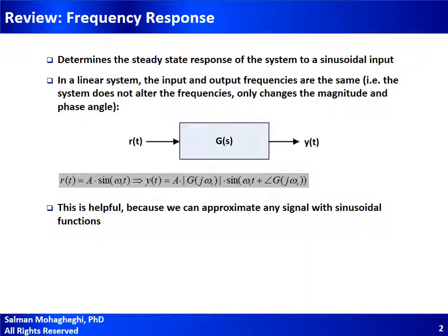First and foremost, what is the importance of Bode plots? You remember that if I have a system g of s, which is being excited by an input which is a sinusoidal function, the output is also going to be a sinusoidal function at the same frequency. However, it will be scaled and shifted. So in this particular diagram, you can see that I have a g of s, and I'm assuming that I have an input r of t, which is a sinusoidal function, a sine or a cosine, and this is my y of t output.